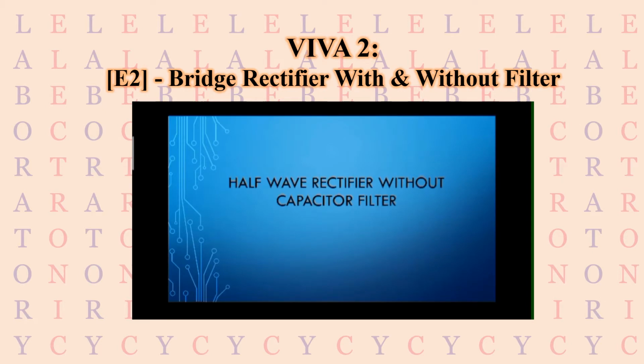In the first part, we do the simulation about the half-wave rectifier with different load conditions without capacitor filter, followed by the half-wave rectifier with capacitor filter. In half-wave rectifier, the DC output might not be constant because of the unnecessary ripple in output voltage. The ripples are the unwanted AC part present in the output DC.